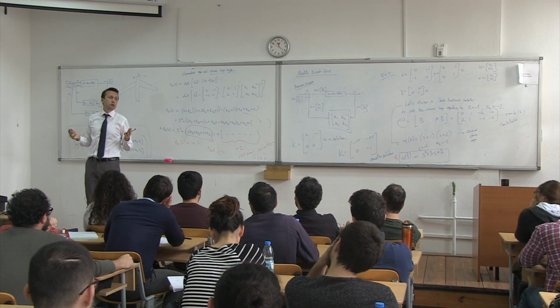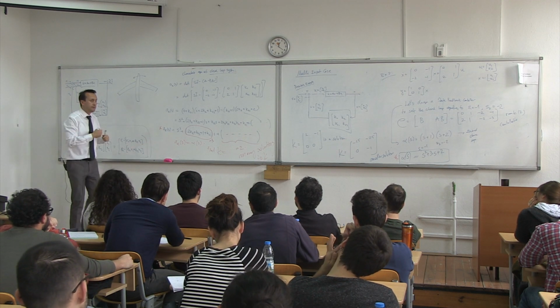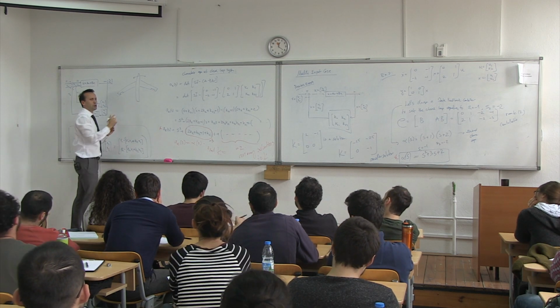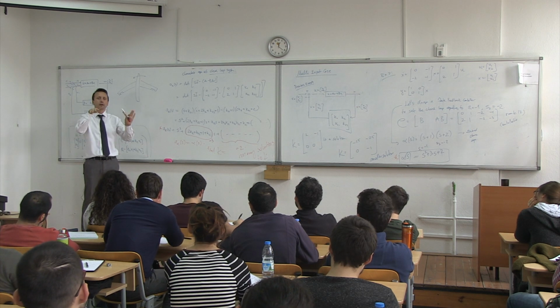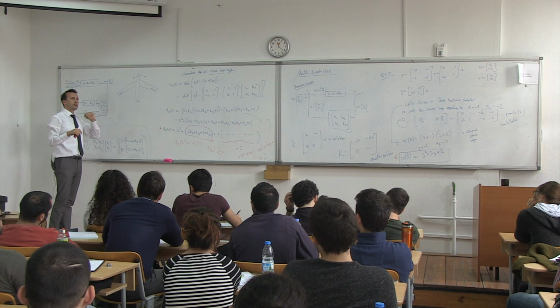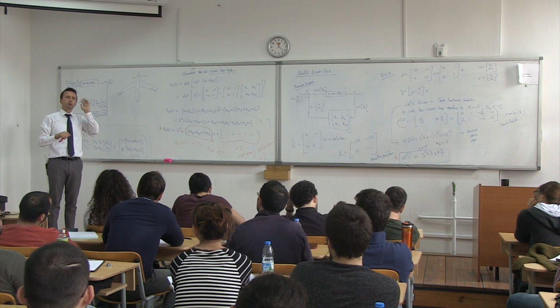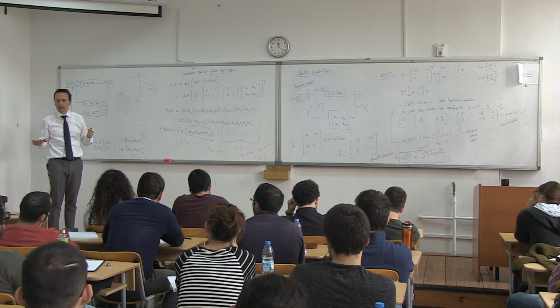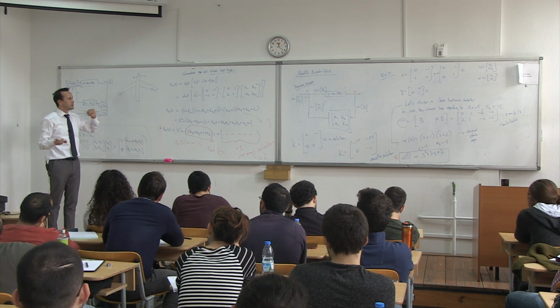What does control the roll? The ailerons, right? So this is your control. It looks like two controls, but it's really one control because they work in symmetry. Okay? So when I say ailerons are 2 degrees, it means one is 2 and the other one is -2, something like that. All right? So you have one control.